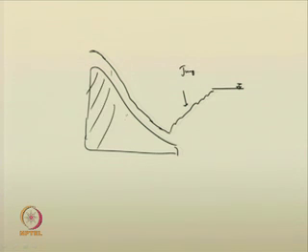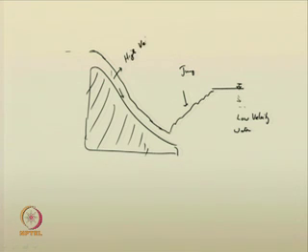Water flows over the spillway at a high velocity, and there is a low velocity depth here. This low velocity can be maintained by various basins, which you can incorporate. Once this low velocity depth is available here, it causes a hydraulic jump. So, we can say this is low velocity water here, and this is high velocity water.